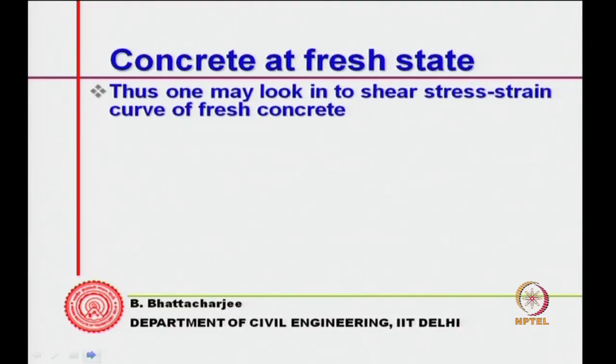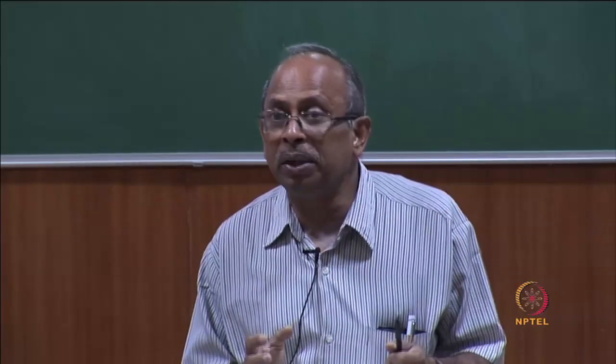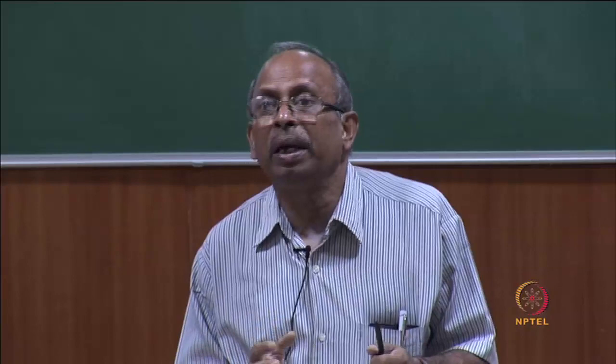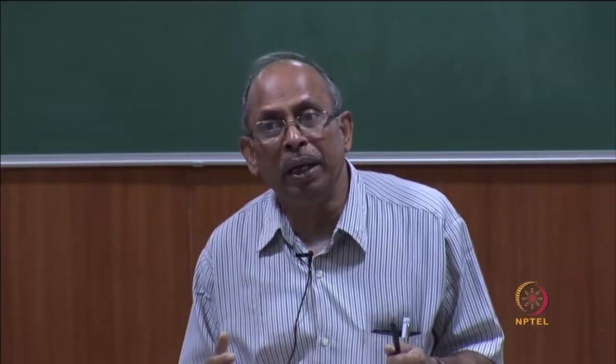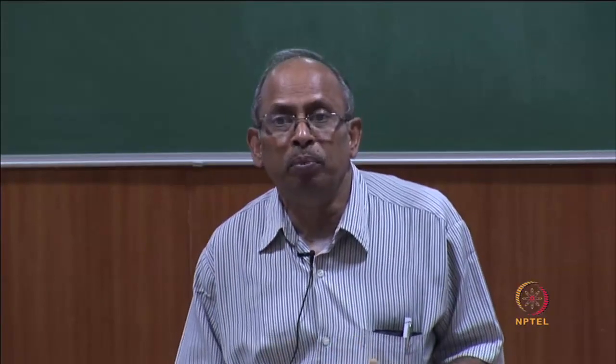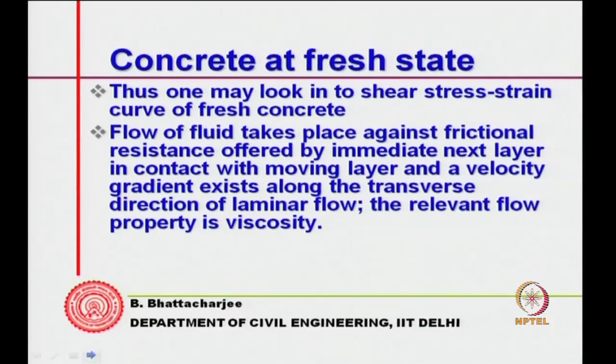So, we must therefore look into the shear stress strain behavior of fresh concrete, because we said that while compacting we apply some kind of vibration, and under the vibration it is subjected to a kind of shear stress, and at a given particular shear stress it will start moving, and then the mobility, the flowing would start. So, you can look into this behavior of fresh concrete. Now, if you look at it, it has to have flow.